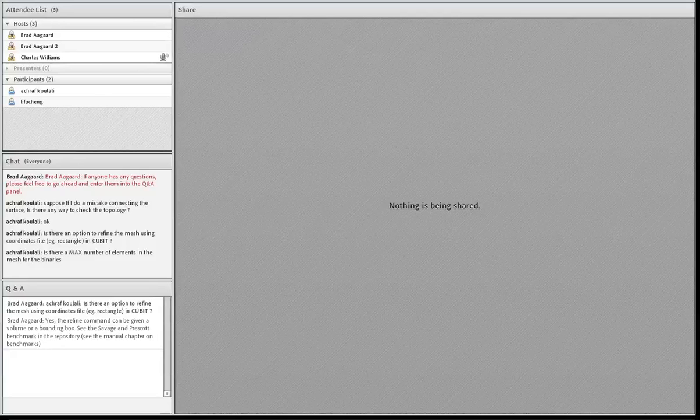If you're trying to generate a really big mesh, then the recommendation is to get everything set up using the GUI, but then you can run in batch mode without the GUI. Without using the GUI or graphics, it'll use even less memory when you generate the mesh. So you can really try and maximize the mesh size.